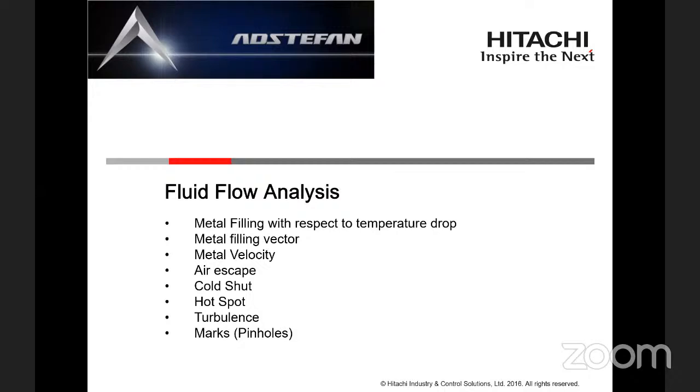Third is the mold material, whether sand mold or metallic mold. Next we need the pouring temperature, then the filling time and mold temperature. These 5 to 6 parameters are needed to start the simulation. All the other required data is there by default in the software.